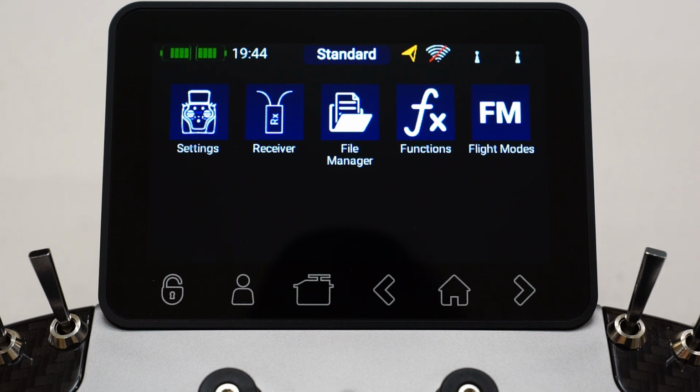You wanted the motor to basically reduce to a set speed, or in some cases, if you're doing 3D like we do nowadays, you want the actual throttle to increase. So as you bring your throttle stick, say below half stick, in a lot of cases these days we actually increase the throttle. And using flight modes was a convenient way to have a different setup on your throttle stick, and also for your pitch curves and all that sort of stuff.